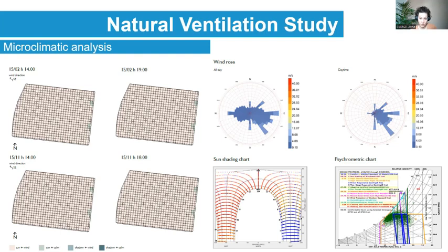To optimize building orientation within the site, a windrose analysis has been conducted to highlight the most common wind direction during the daytime, while with the sun shading chart plot, the position of the sun in the sky is linked to the dry bulb temperature, red the hottest hours and in blue the coldest hours highlighted in the diagram, to identify shadowing strategies to prevent overheating or enhance sun radiation collection during the coldest hours.